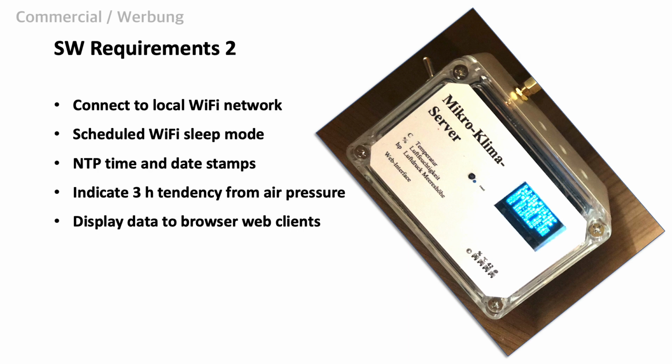Going on with our software requirements. We want to connect our web server to our local Wi-Fi network and of course manage our credentials. The function that I called scheduled Wi-Fi sleep mode means practically that we can define an automatic switch off time in the evening and a wake up time in the morning. Of course, the LoRa receiver and the data processing needs to run continuously, also when the Wi-Fi is switched off.